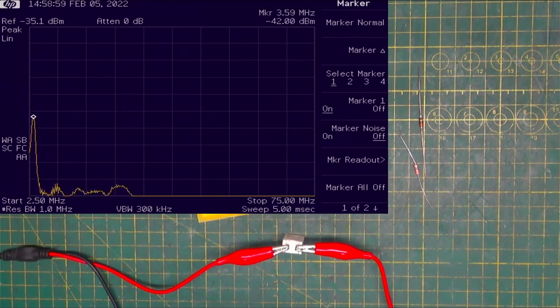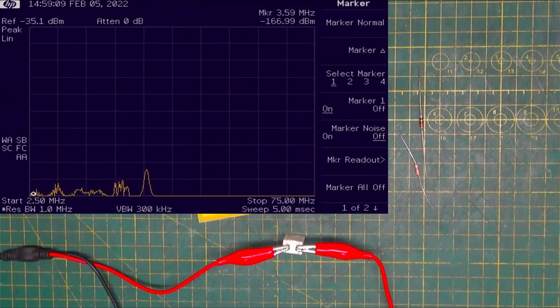All right, so let's start sweeping that across a little bit. And, oops, it's going down quickly. It's dropping like a rock. So let's get up to 28 megahertz, someplace around there. Remember, at 28 or 30 megahertz, we're down 50. So we've already lost almost 10 dB.